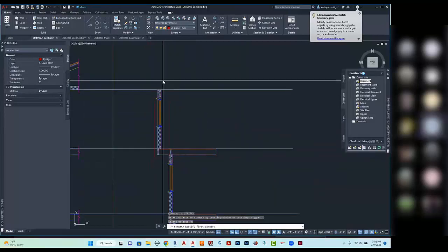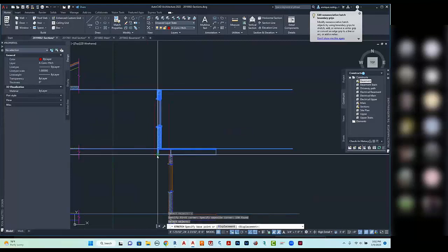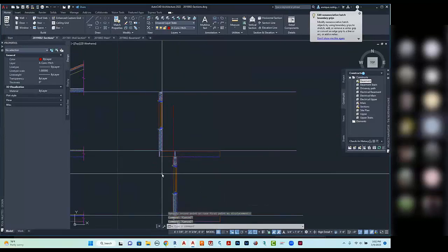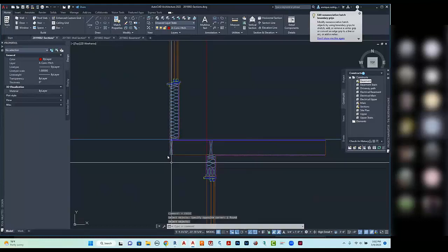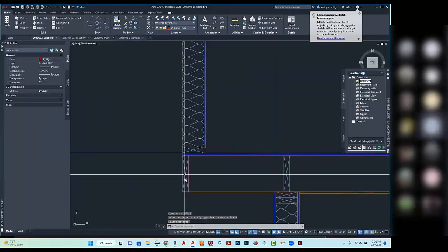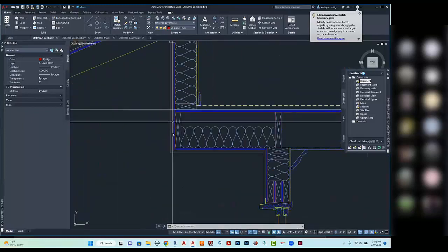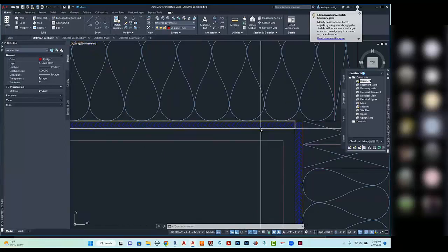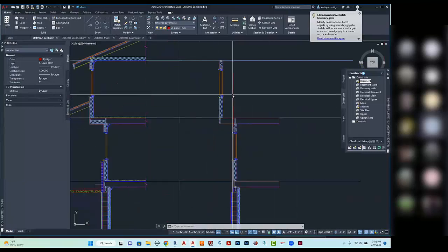I'm going to use a stretch command. I'm going to stretch all of this, from this point to there, with my 2 foot overhang. Now turn it off. And I'm going to go ahead and lay some plywood out and wrap it all the way around in here. Probably can use 1/2 inch here also. Again, there's no load really coming down on that.